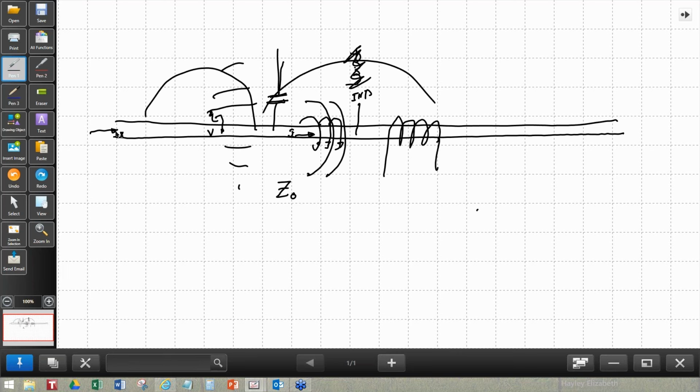It's important to know that these electric and magnetic fields are coupled. If the voltages stored in the capacitance are left for a period of time, they will cause current to ramp up through the inductor. Hence, there is a propagation speed, which is less than the speed of light by a factor of the dielectric constant. So we have a classic transmission line with all of these things active.